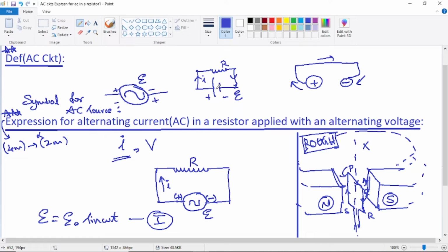Now what does Kirchhoff's voltage law state? The statement is very simple. Suppose you are going around a circuit completely once. We'll take the simplest circuit here. Labeling of the circuit is not possible because the diagram is too small, so I'll present the topic diagram again. Let the circuit be named A, B, C, D, A. In this closed circuit A, B, C, D, A, Kirchhoff's voltage law is applicable. When an electric field, a conservative field, is present, the voltage law is derived based on its conservative nature.